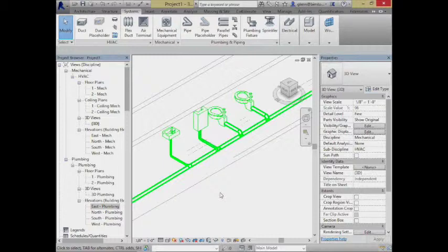What auto routing is not really great at doing is, if you give it an awful lot of freedom to make a connection, and there are many different options in which it can be made, it may not always make what you would consider the smartest choice about how to route things. Like if I just took those pipes and said there's a riser over here, route them together, it might not run it through the wall and do something sensible like that. It might just try to do something that it thinks is mathematically a shorter path.